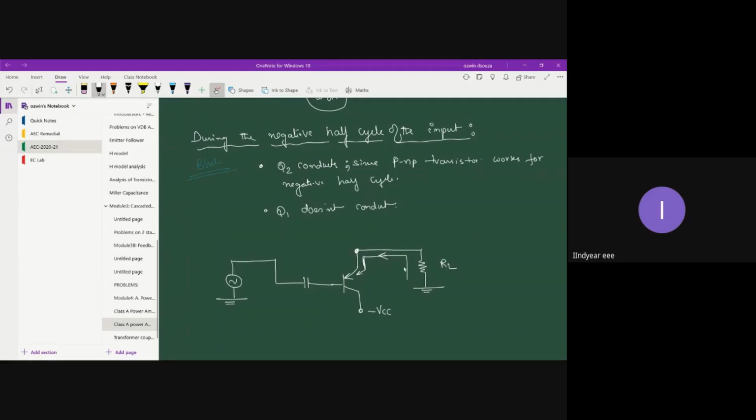So you can see that the current is reversed, right? So that's the reason your V0 polarity, if you look carefully, the current is entering from the bottom side, right? So this is positive and this is negative. That means to say the V02 is going to be a negative voltage.